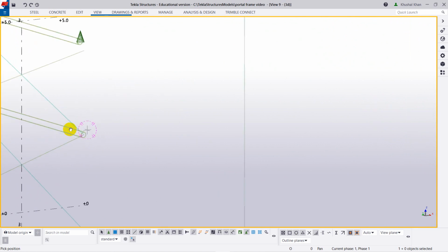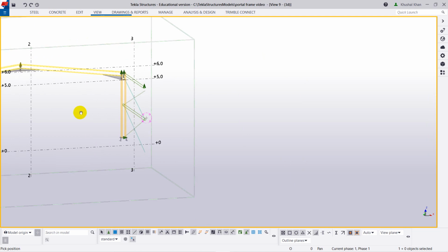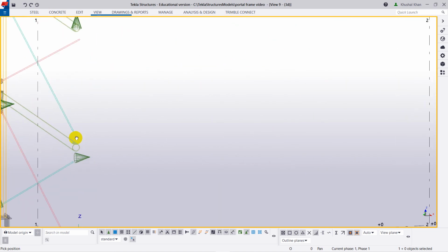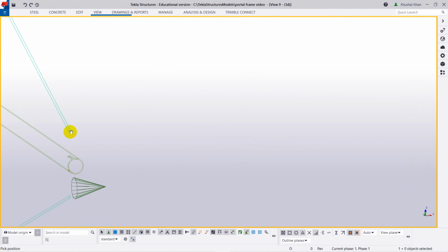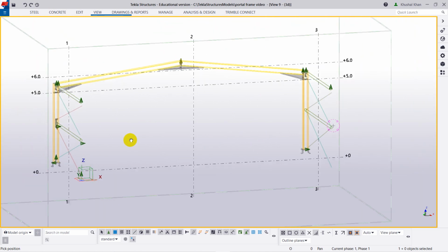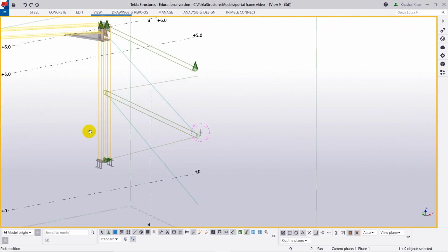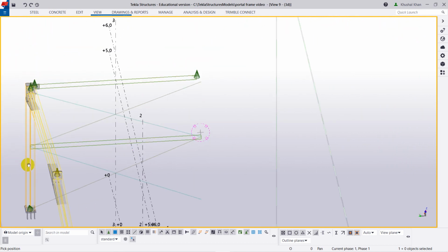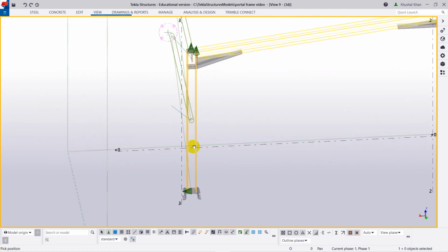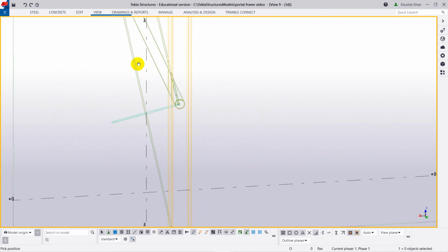This is important while you are modeling in Tekla, and you have to create the views and check everything. Don't worry about this one, because it's completed; it's not showing because there are connections. This one is centered, so we don't need to fix them. If yours is not fixed, you can follow the steps I'm doing here for this one, and repeat for the other side.